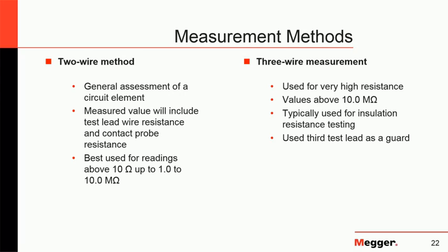These two that you have, I wanted to start this section with these two measurement methods that you have on your screen. The 2-wire and 3-wire methods are not meant for making low resistance measurements. But I wanted you to have this in mind so you can identify them, and any day you see a tester with either 2 wires or 3 wires, you will know that those testers are not meant for taking low resistance measurements.